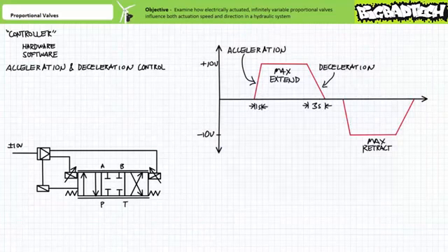But I digress. As previously mentioned, the pressure shock associated with a traditionally fully closed or fully open directional control valve can be mitigated by proportional valves by smoothly ramping applied voltage up or down over a time period, thereby slowly opening or closing the valve and suppressing the shock.